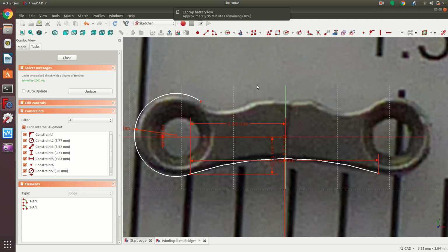Okay. Now we can go in for the circle. So we have a circle here. Did you measure the screw there? Yeah, I measured the screw head and the screw thread. What's the thread? 0.6. Okay, so we need 0.3 radius and a tiny bit more. I'm not quite exactly in the middle. If you look at it, you can see the circle is a bit too far to the left. I'm going to move it over a tiny bit to the right. Yep.